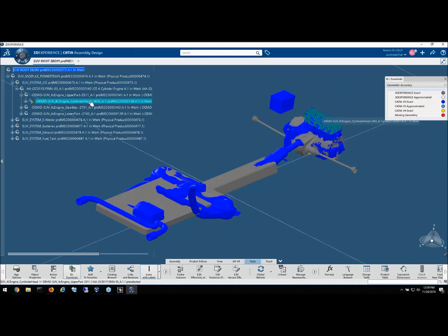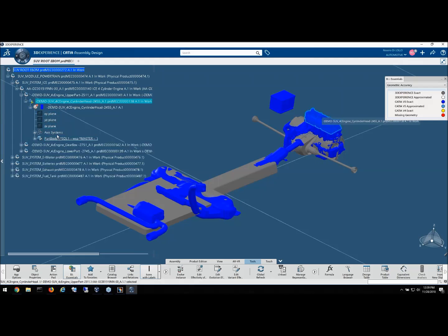And if I open this 4-cylinder engine head, which was basically Catia V5, you can see that underneath the 3D part, I'm going to have the 3D shape, and I'm going to have this no entry element, which is going to tell me it is a 3D shape, but it is a Catia V5 3D shape. So even if the system has exposed the design features underneath it, since it's Catia V5 native, obviously, if I want to open it or if I find a clash with it and I want to modify it, I'm going to have to open it in Catia V5 to author it.